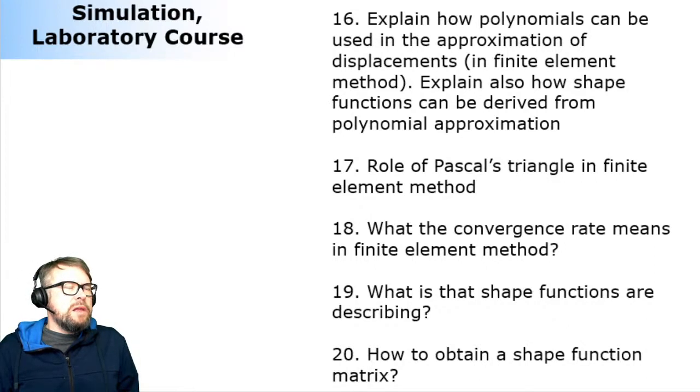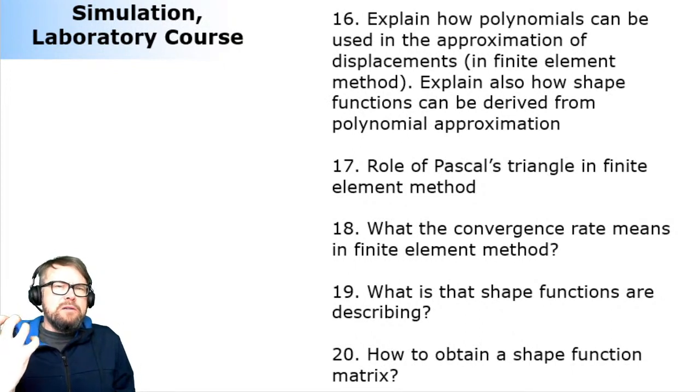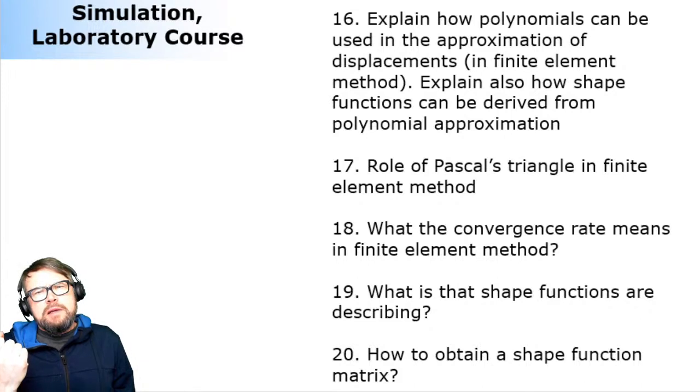This is all about the finite element method. This, by the way, is like the core of finite element modeling. And the core has consequences. So when we are describing the displacement using polynomials, we end up with something that is called the shape function matrix, or shape functions. How those shape functions can be derived, that's what I'm going to explain to you next.